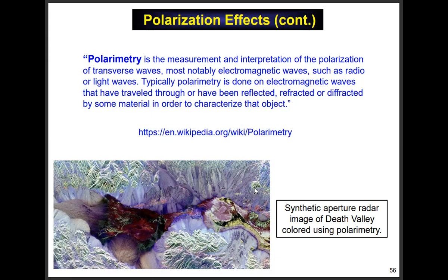When a wave goes through the ionosphere, the ionosphere will rotate the polarization. How much depends on the frequency and the thickness of the ionosphere, which depends on the time of day and various things like that. So to be really safe, they like to use circular polarization.